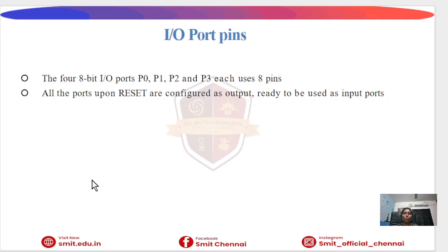Next one is the input output port pins. The 8051 has 4 input output ports, that is P0, P1, P2, and P3. Each port has 8 pins, so total 8 into 4, 32 input output lines. After reset, all ports are configured as output, but they can also be used as input. Port 3 pins have special functions like interrupts, serial communication, and timers.